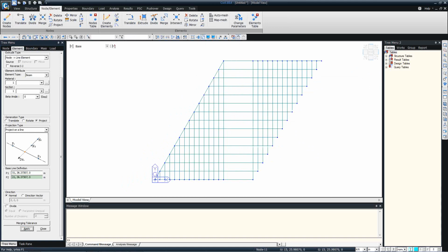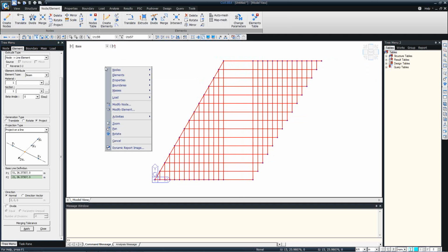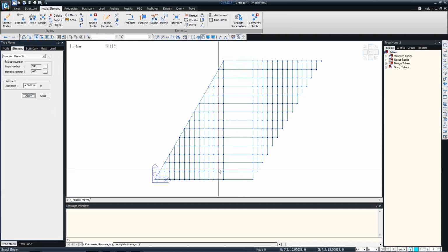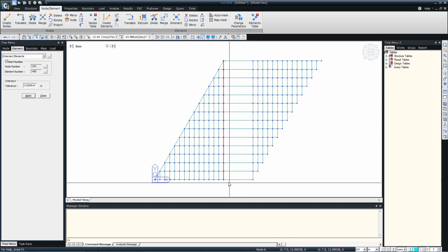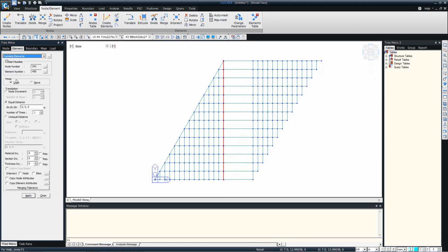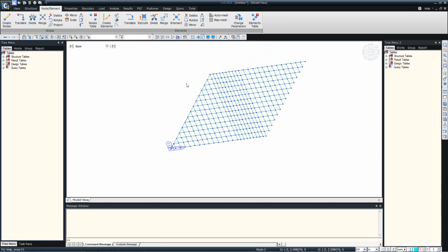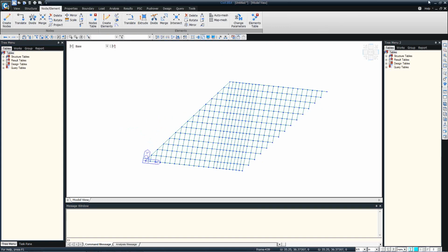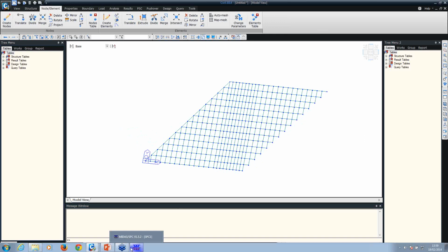Now for in between, we need to make sure that they are intersected properly, so I'll select everything and elements and intersect. So they are intersected, and just to fill up in between, go to translate elements and just measure the distance, 9, 8 times, apply. So that's your transverse grillage modeled, and you can start assigning properties or sections to different parts. So that's how quickly you can generate the orthogonal grillage.